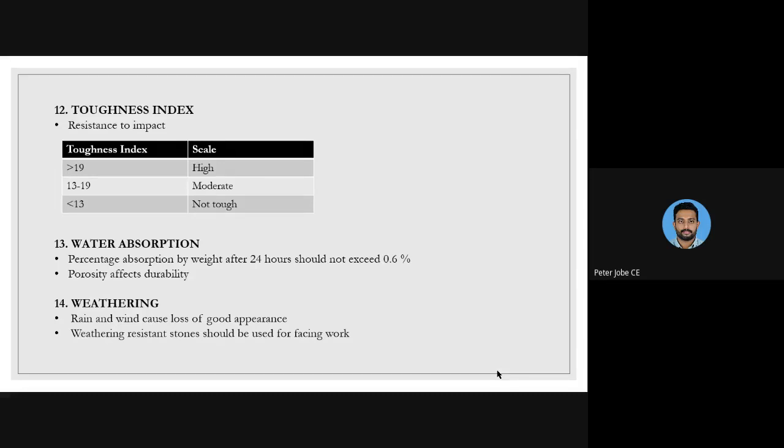So in case of roads, especially, there will be a huge impact, and also in places where sudden forces are expected, it is considered to be an impact. If you are designing a road or bridge, etc., we'll give an impact factor of 25%. That means we'll multiply the expected load by 1.25 in some cases. And the impact factor will change depending upon several factors.